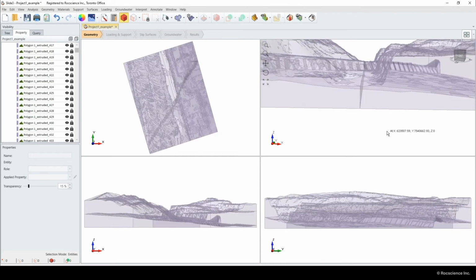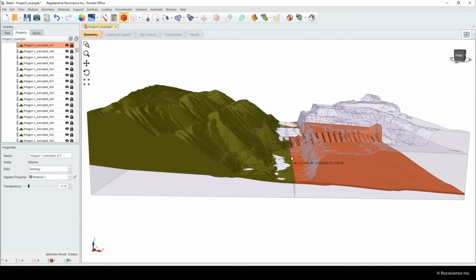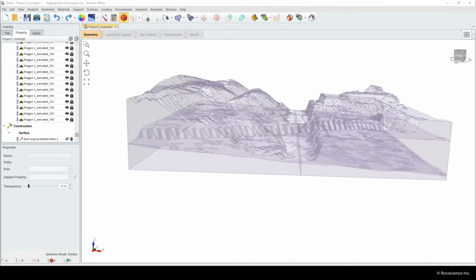Zooming in on our newly created volume for the D12 seam, understand this is a pretty sharp edge for the D12 seam, which is likely not true in reality, but conforms to the geometry files that were imported and divided all into the model for demonstrative purposes. Depending on how uniform or undulating the surfaces of entities are that are imported into the model, it is recommended you check the number and the location of small volumes that were created after each divide all process.